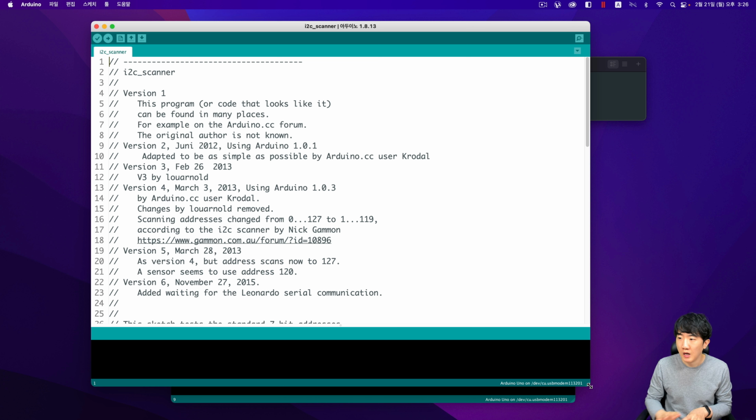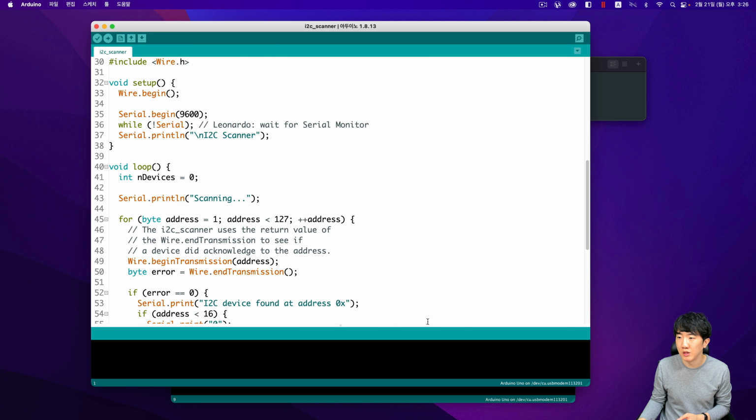If you searched and nothing comes up, it means there is a problem with the hardware connection. In such cases, you should check whether the communication voltage is correct, whether it is 3.3V or 5V, or if there is a level converter that allows for compatible voltages. Additionally, verify that the SCL and SDA pins are connected correctly, that the ground pin is properly connected, and whether external pull-up resistors or the resistor connection conditions required in the datasheet are met. It is a good idea to check these things.